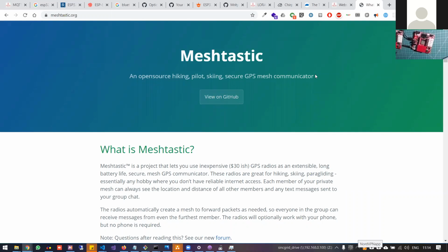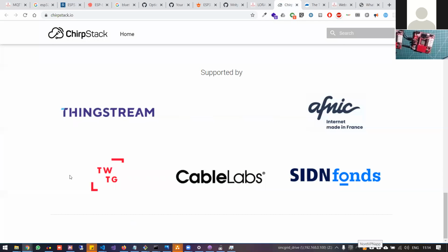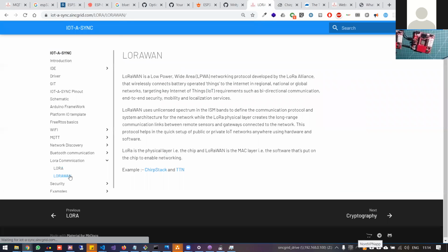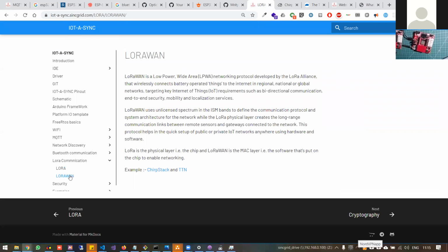In this unit, you are basically using a single channel for communication. But the advantage you get in LoRaWAN is that you are using a band of channels available to you. The full band you are utilizing. There are multiple channels available, and to overcome congestion and collisions at a time, they have something called listen before talk, and these kinds of algorithms are available so that congestion can be avoided.